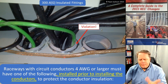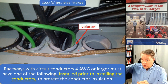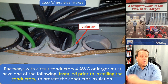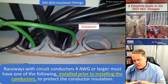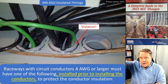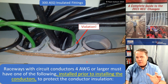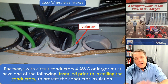So here in the picture, wonderful example of why this code rule exists. You have to install a plastic bushing or something to protect the conductors from the sharp edges of the raceway and also to protect the raceway itself from the process of pulling the conductors. So you have to do this before you pull the wires. If you install a protective bushing after the wires are already installed, you're shutting the barn door after the horse is already gone, right? The risk that we're trying to address, the hazard, only exists during the process of installation. So there's no reason to pull the wires through and then add a plastic bushing.